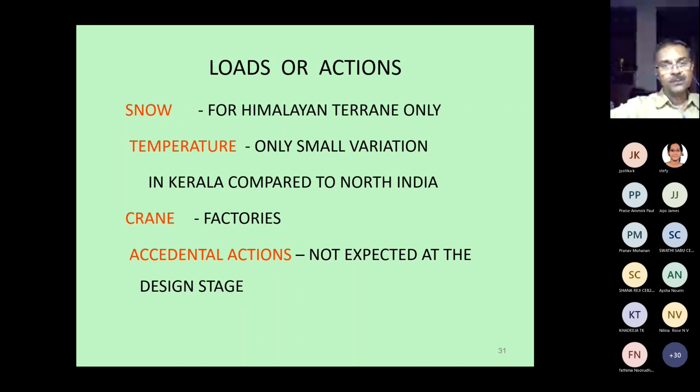Now coming to another type of loads, it is the crane loads. If you take factories and similar structures, we need to install certain cranes within the structure to handle the materials coming in, or for factories to handle the machineries and things like that. So the crane is again a dynamic load wherein it picks up a load very fast, creating an impact on the structure. So it's an electric crane, and once we switch on, the load is carried by the crane in a momentary fraction of a second, which can generate an impact on the structure.